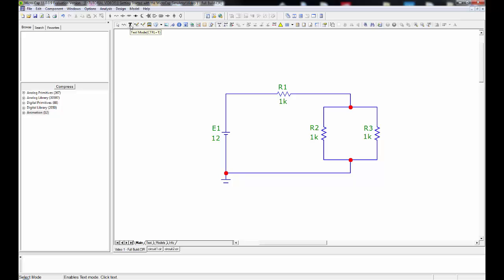Text tool here, so if you want to put headings in on your schematic, or markers, or record some note or whatever on your schematic, just click on that and put it into the area that you want. Hey presto, you can change the font and the colour and everything. The wire tool we've already seen. Diagonal mode wiring, that's useful when you have that 3-phase circuitry in place.